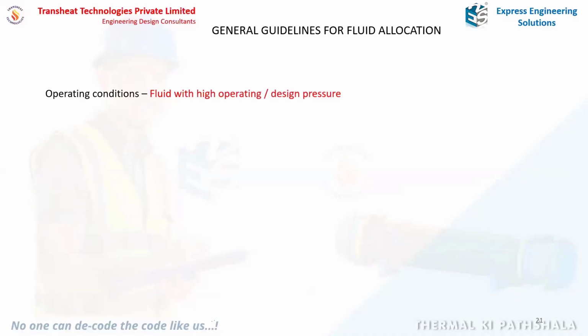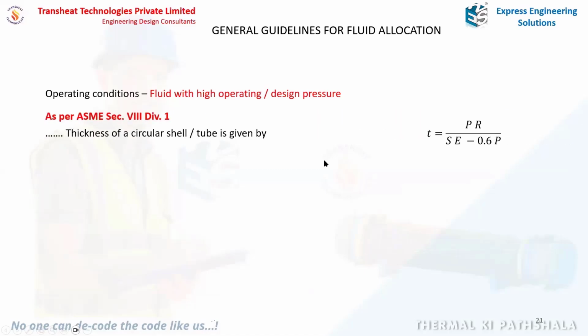Now, what do we do when you have a fluid with a high operating pressure and a high design pressure? Here it's got to do with a little bit of mechanical design. This is the formula for thickness of any circular component as per ASME Section 8 Division 1. Whether it is for a shell or a tube, P is the pressure, R is the inside radius, E is the joint efficiency, S is the allowable stress value for that material, and again P is the pressure.